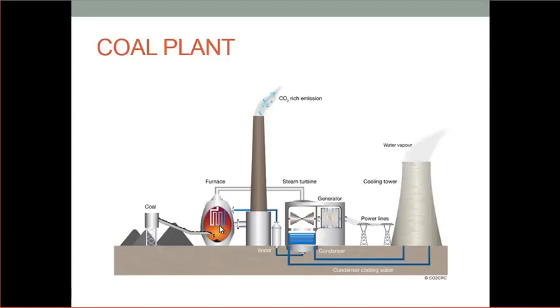In a power plant, we talk about heat rate. So the heat rate is the number of million BTUs of heat you put into it, and then the amount of megawatts you get out of it, right? So it's megawatts per million BTU. So that's your fuel efficiency. It's like your miles per gallon.